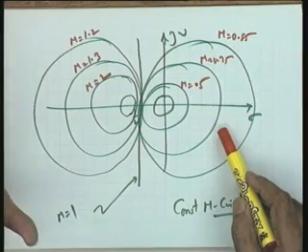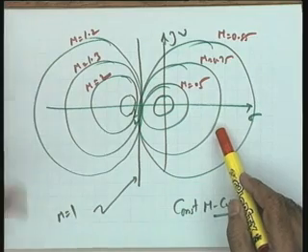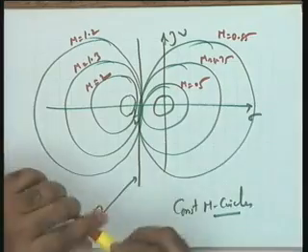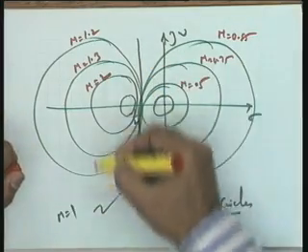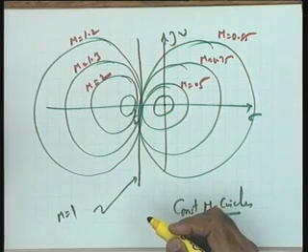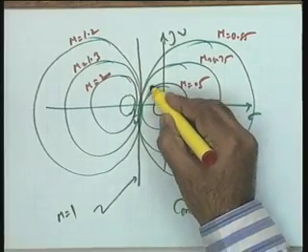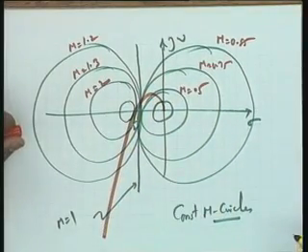I have drawn a locus, the loci of constant m, where m is the magnitude of the closed loop response. Now, if I have these things available, on this particular plot you superimpose your open loop frequency response. The open loop frequency response is available to you, so let us say I make a polar plot of it.